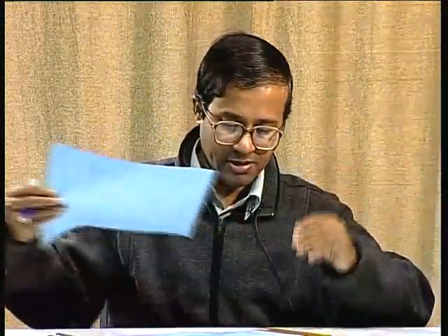At the logic level, in the pre-layout simulation phase, interconnect delays are assumed to be 0. They are all ideal interconnects. Only at the level of post-layout simulation can you take care of that. Yes, you are right, that we are ignoring. Fine. So now let us again start by looking at very simple examples.